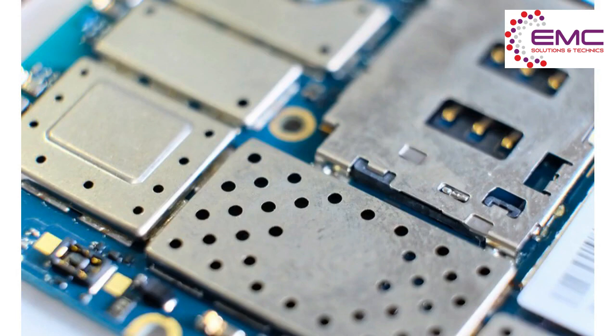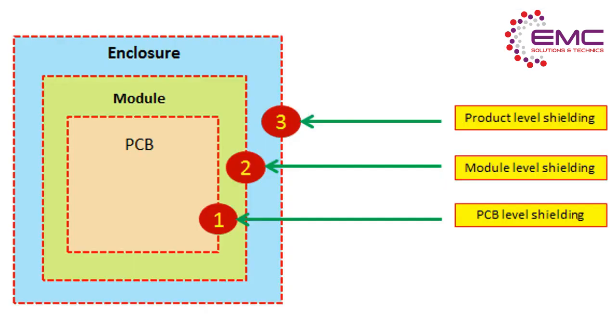A shield is like a closed conductive container connected to ground which effectively reduces the size of loop antennas by absorbing and reflecting a part of their radiation. In this way, a shield also acts as a partition between two regions of space by attenuating the radiated electromagnetic energy from one region to another.